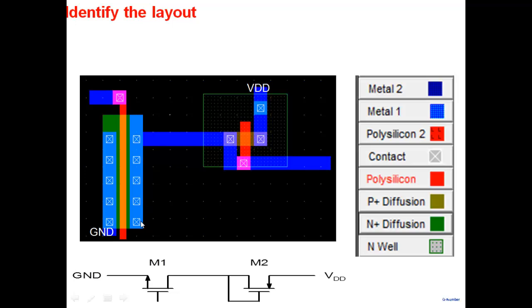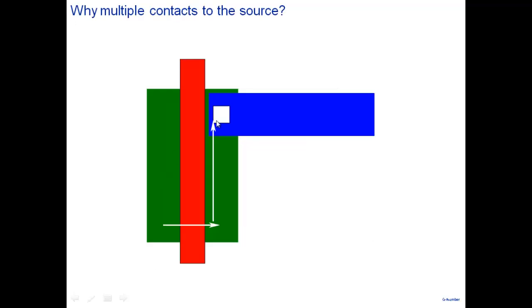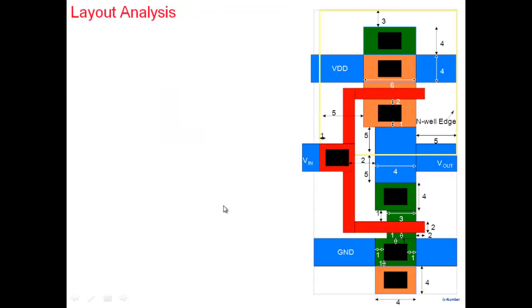Now, who decides the width of the MOSFET here? This is the width of the MOSFET. That's coming from design. When you do a schematic design, you say, well, I need a MOSFET 20 lambda by 2 lambda, whatever. So the width of the MOSFET comes from there. Once you decide the width of the MOSFET from the design, after that, in that width, try to accommodate as many contacts as possible. Okay, in this case, the width of the MOSFET is small, and all that could be accommodated is one contact. You don't want to make an area larger just because of the contact. But if you have a certain area available, put as many contacts as possible. Don't draw a layout like this here, and leave this entire area empty and resistive here.